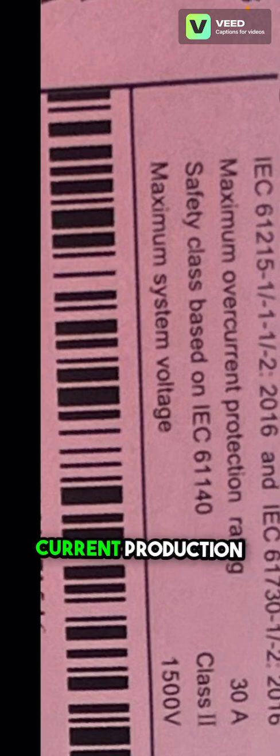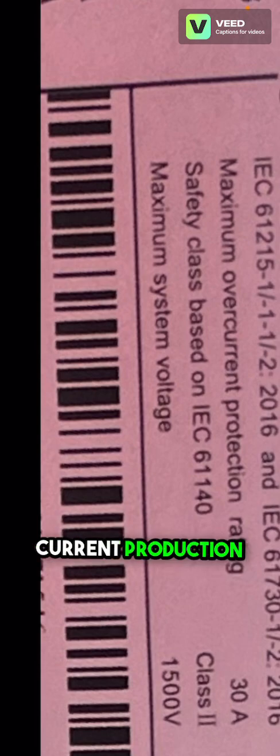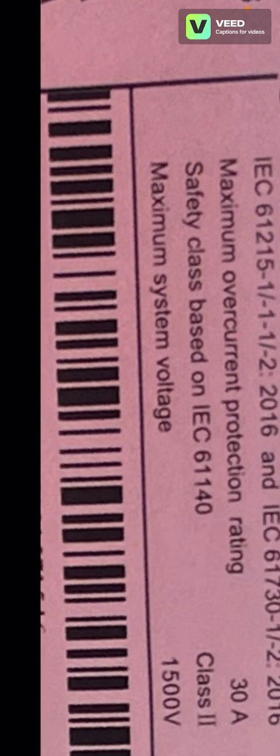Maximum fuse rating. Maximum fuse rating means maximum overcurrent protection rating. Here you can see maximum overcurrent protection 30 amps. This means the DC fuse or MCB connected to this panel should not be more than 30 amps. This protects the panel from reverse current during fault conditions.